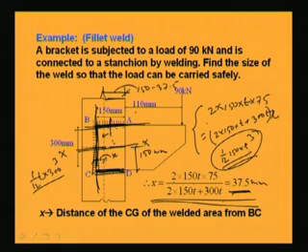IYY: first I have to calculate in this direction, at the middle, 1 by 12 BD cube, then transfer to this distance for these two, top and bottom.